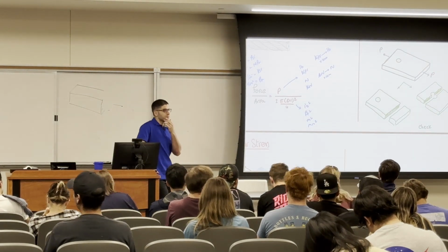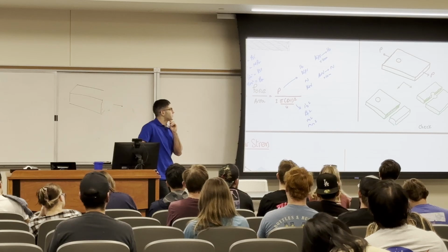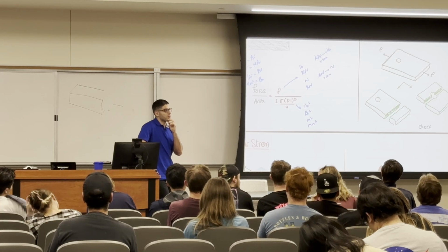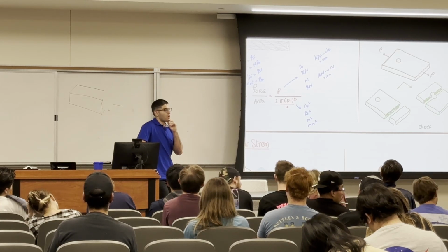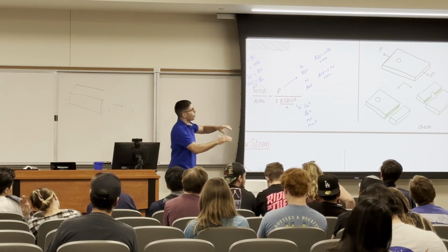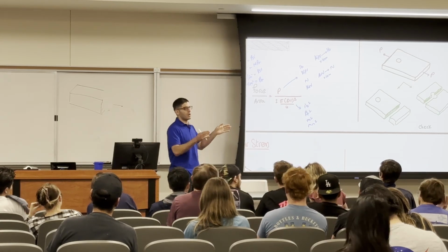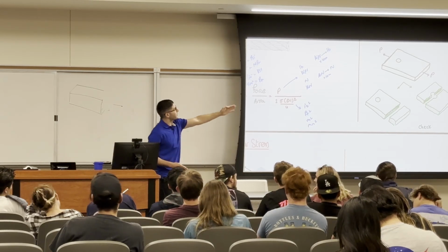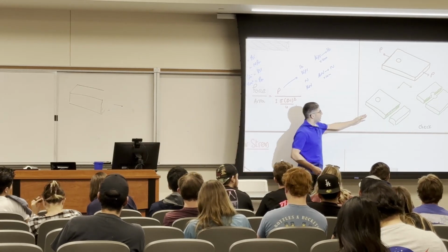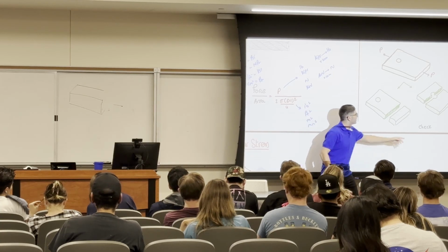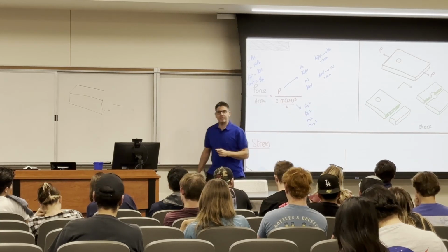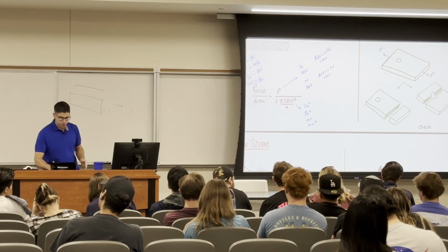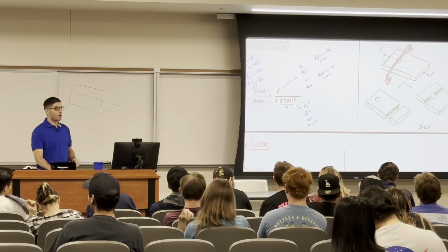Tell me. Is that only if the forces are where they're shown right there, or can the bigger cross section have a spot where, if the forces are in this spot, it'll kind of go? Oh no. What I'm saying is the whole plate is subjected to the same P, constant force. I'm not changing the force. Later in the class, we will be changing the force. But if I have the same force and you have different cross sections, you can check both areas. But I want you to know before calculating that this one will give you higher stress. So whenever you see a hole in a plate, you need to focus on that cross section, which will give you a higher stress.